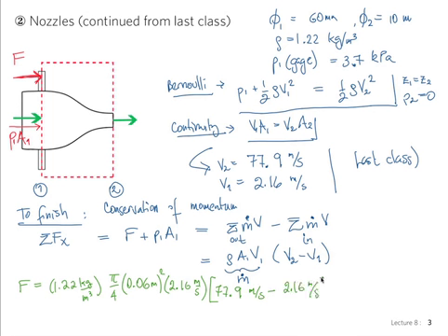And then I'm going to take this, of course, to the other side, and it's minus 3.7 kilopascal times A1, pi over 4, and again I have 0.06 meters squared. So all of those values are now available, right? I can put all of those numbers in the calculator and obtain my result. I've done this ahead of time to save some time, and I get minus 9.9 newtons.